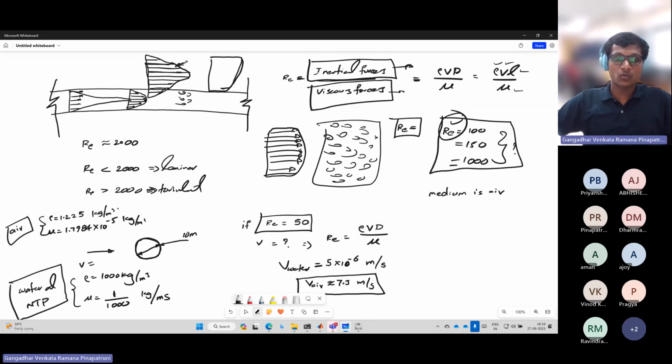Air with density rho equals 1.225, and density rho we know, velocity we know, and temperature. Sorry, no need of temperature. We are not going to handle the temperature in these governing equations. We are keeping the temperature constant, and viscosity we know. Pressure also we know. We set it as atmospheric pressure at the pressure inlet and pressure outlet boundary conditions, which we will set soon. And the Reynolds number should be 50.